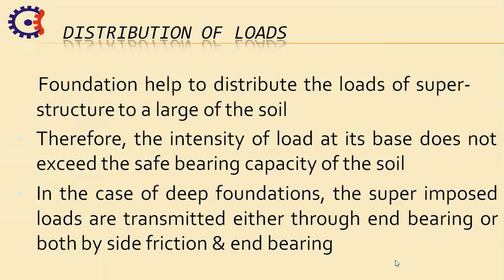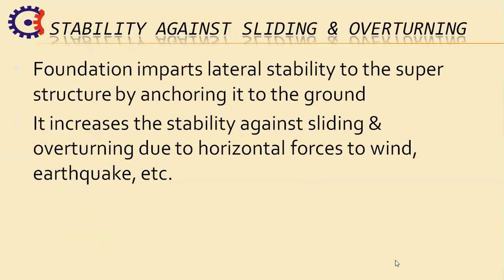Distribution of loads. Foundation helps to distribute the load of the superstructure over a large area. Therefore, the intensity of load at its base does not exceed the safe bearing capacity of soil. In case of deep foundation, the superimposed loads are transmitted either through end bearing or both by side friction and end bearing.